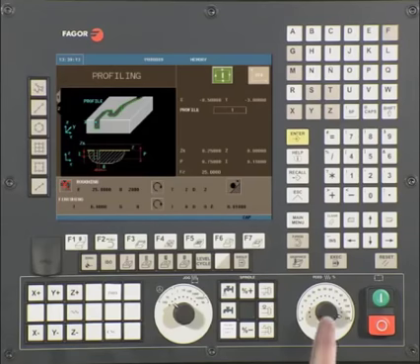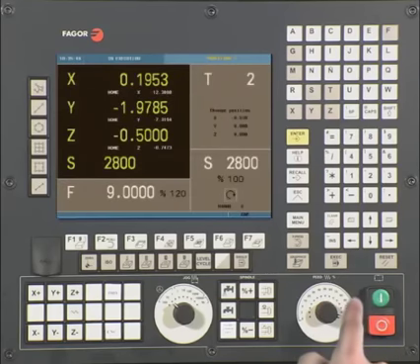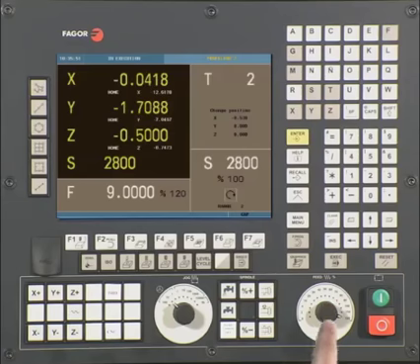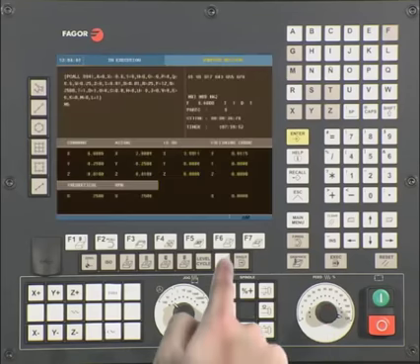Turn down the feed rate to 0 and press the Cycle Start button to begin executing the cycle. You will need to increase the feed rate after pressing cycle start. If gear ranges are an option on your machine, you may be prompted to change to the correct gear. Change gear and press enter to continue. Slowly turn up the feed rate so execution can continue. To see additional information while the program is being executed, use the half key to toggle between basic and advanced screen.